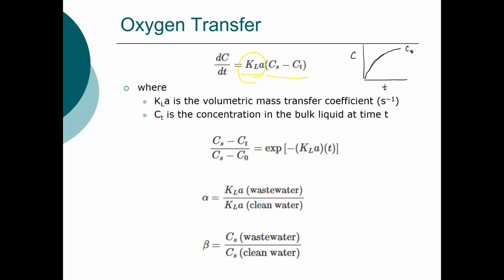For very soluble gases, such as ammonia, the principal resistance is in the gas phase, which means that we want to make that gas film as thin as possible. Mixing the liquid isn't going to change things a whole lot, because mixing the bulk liquid in order to reduce the liquid film isn't going to change things a whole lot.